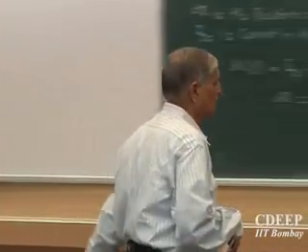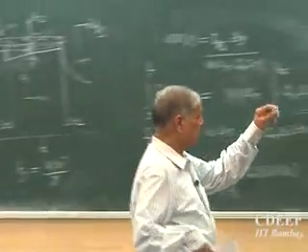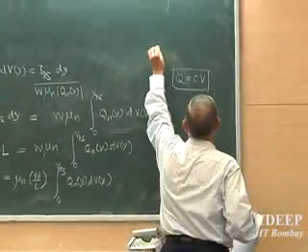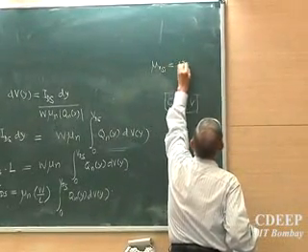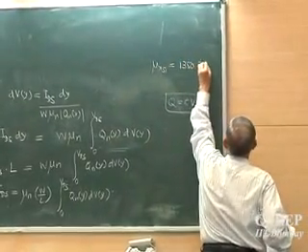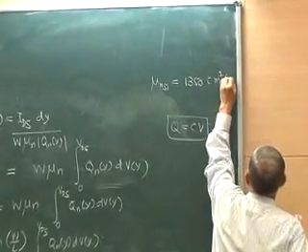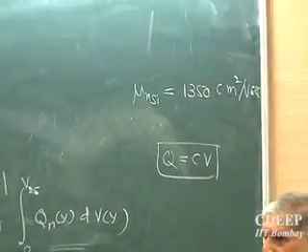So the actual carriers never move with that much mobility. It's called surface scattering. So the word is surface scattering. The mobility at the inversion channel: what is the bulk mobility for electrons in silicon? What is the number I gave you? 1350. Of course that can vary from book to book, but typically assumed value is this.